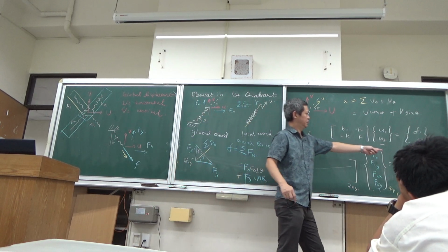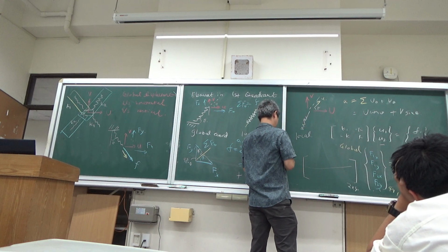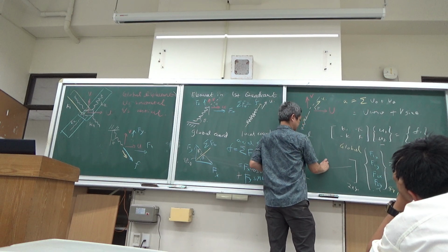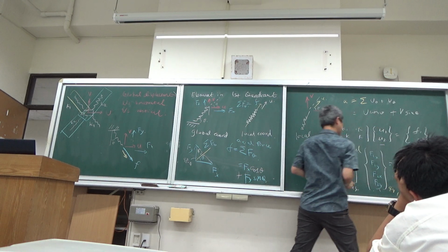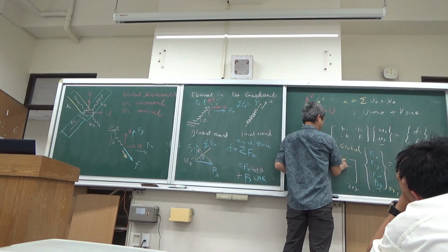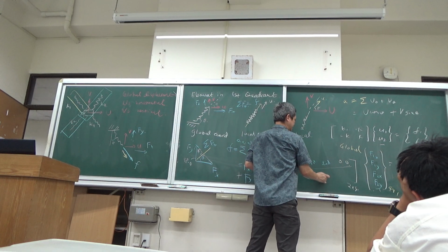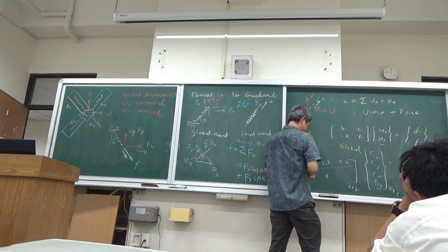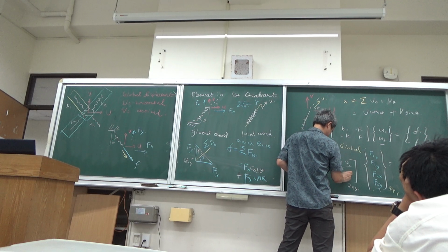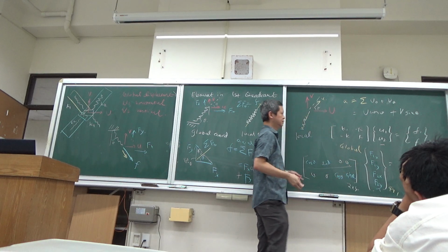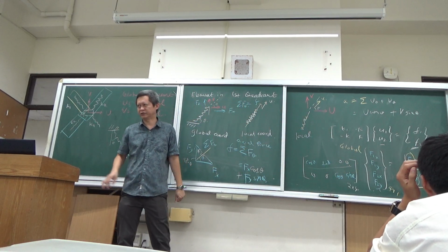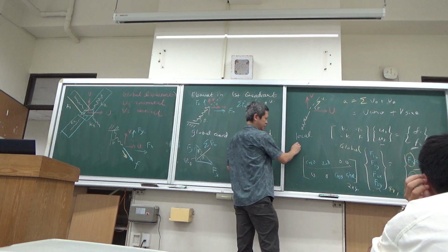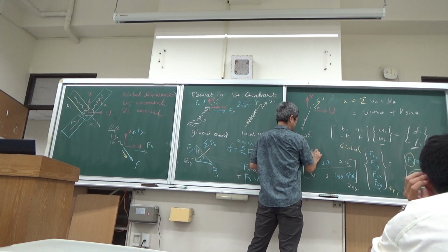The first one is cosine theta, sine theta, and it does not multiply forces on the second node. Then in the second row, you only multiply forces on the second node, so it is again cosine theta, sine theta. This is what you call your rotation matrix.